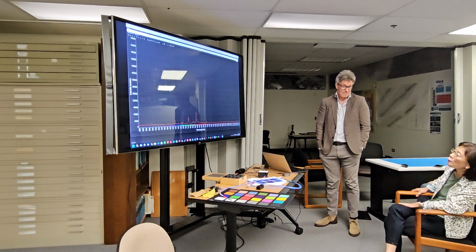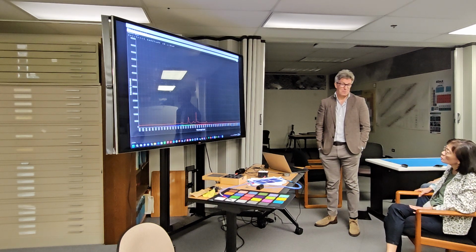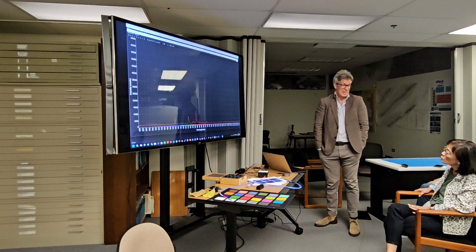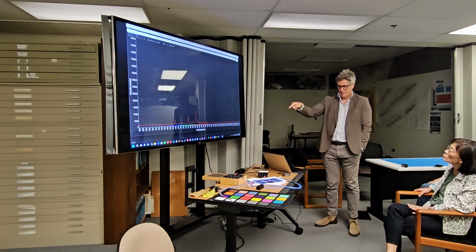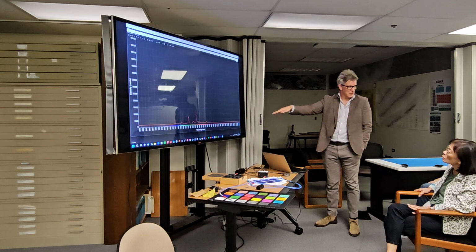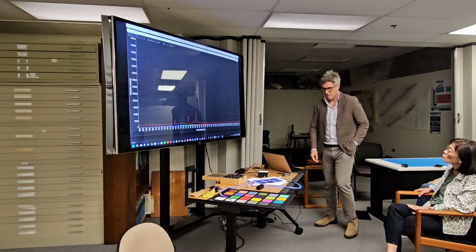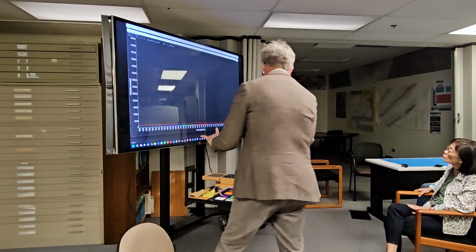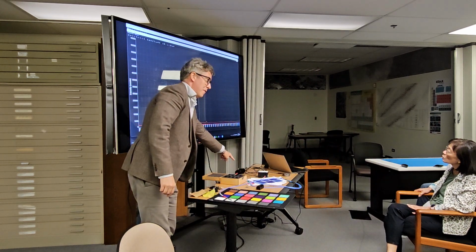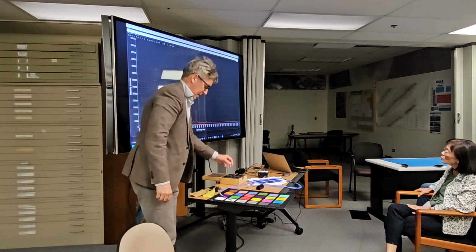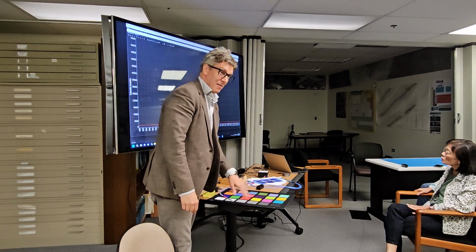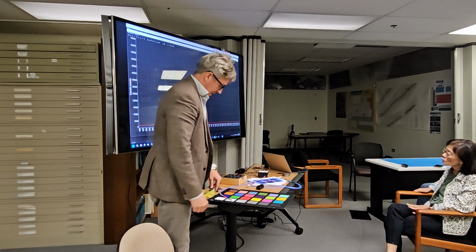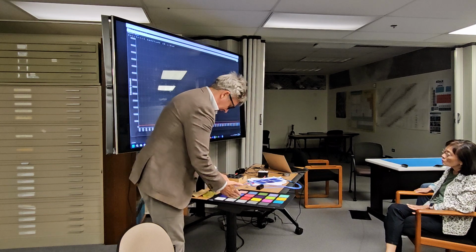So that's basically DN. Sometimes you see counts, sometimes you see digital counts, which would be DC. Sometimes you see digital number, which would be DN, but it's all basically the same. That's the digital representation of the amount of light that the spectrometer is collecting as a function of wavelength. So the light coming out of this thing is fixed and invariant in time, and I know its composition. That light's coming down this leg of the spectrometer, and it's being fired out of the fiber optic at the probe end. And that's happening on the outside.